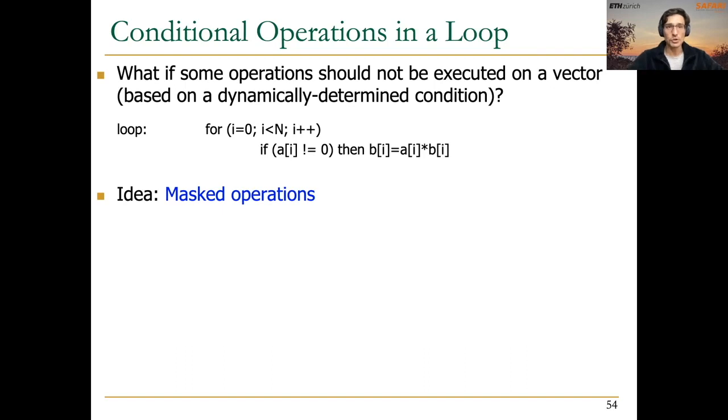But when it comes to accessing DRAM, which is also a banked memory, it's more complex than that. Normally these days, they are using hash functions in order to calculate what's the physical destination. And that's also one of the potential solutions that I'm going to mention in 3 or 4 slides. Okay, I guess I can wait 3 or 4 slides then. Yes. Thank you. We will talk about that more, don't worry.